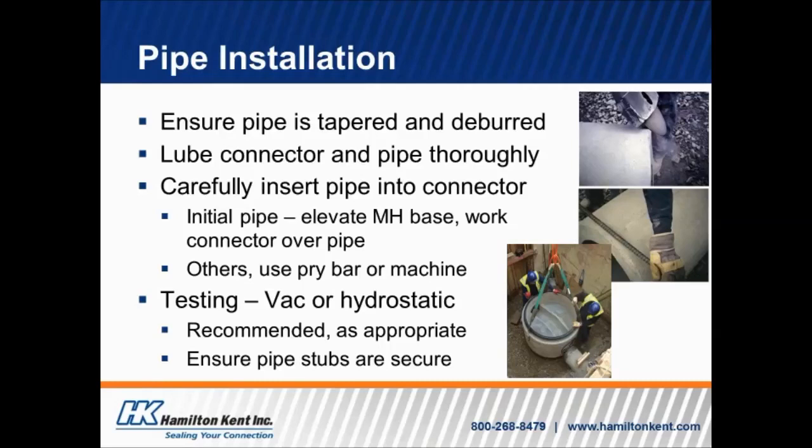And then the second picture down, they're taking a piece of reinforcement and they're deburring. There's a little bit of a seam right there that's showing up on the concrete pipe, so they're deburring that just to make sure that the pipe is very smooth, so that once it's installed into the connector, there's no reason for that connector to be torn or to have an ability for a leak. Then they lube the connector very well and the pipe as well.